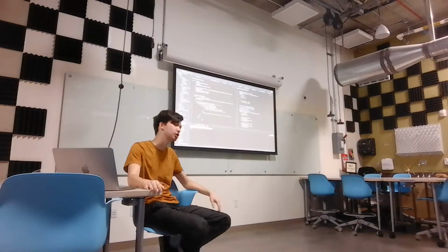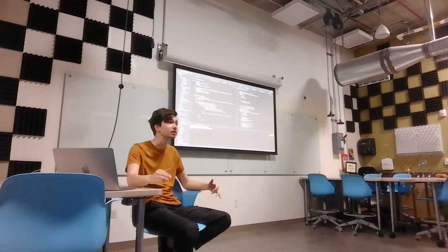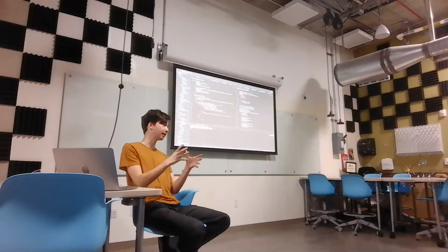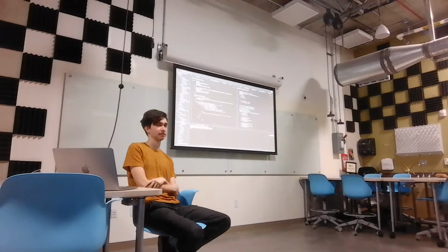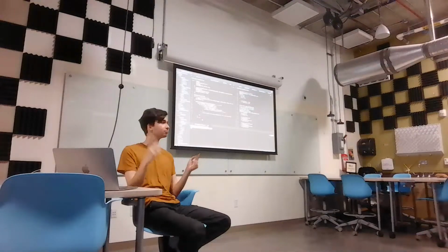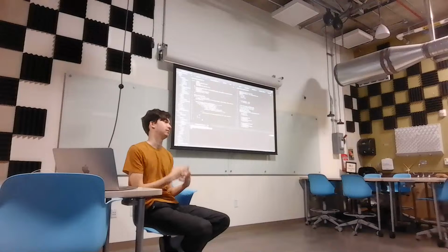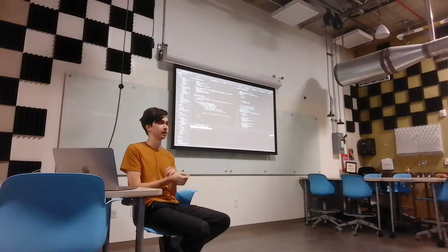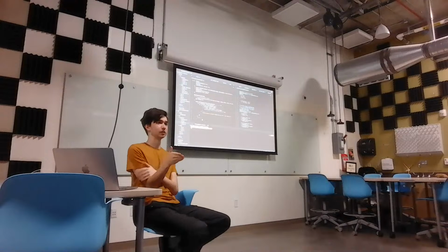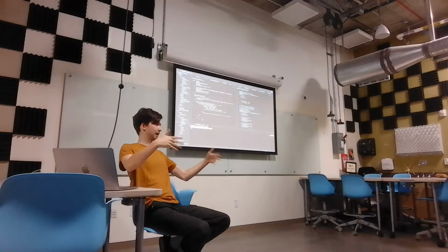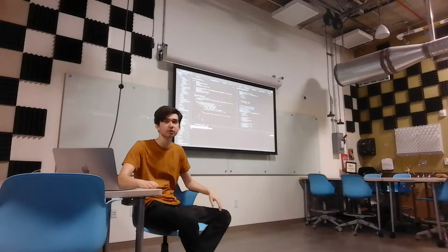So some very smart people developed Rust bindings to the closed source binary that handles all the Bluetooth stuff. That binary is called the soft device. It's this thing Nordic made that knows how to do Bluetooth. You can just tell it how to set stuff up and get events. So you just flash that closed source binary, use this Rust library to get bindings to it, and you can do all the Bluetooth stuff.